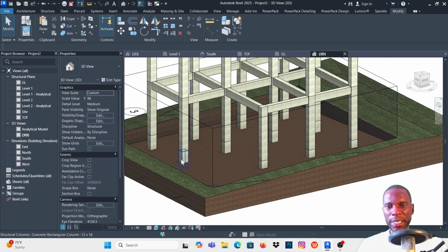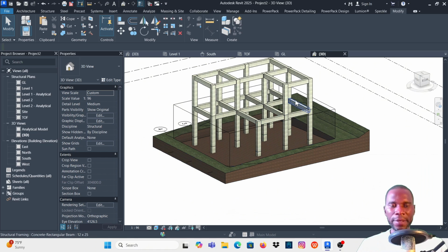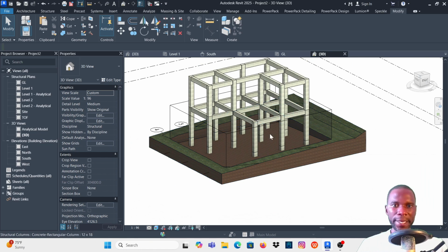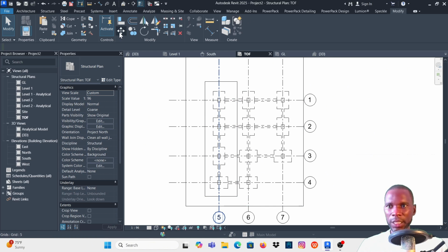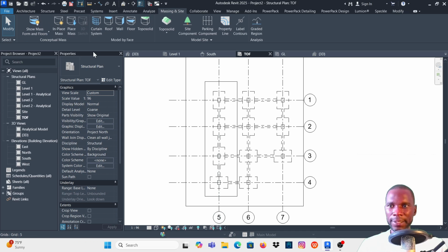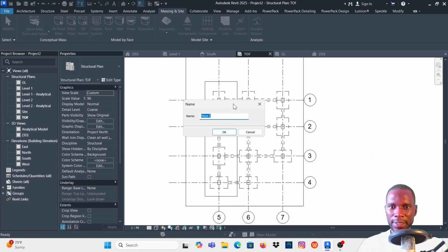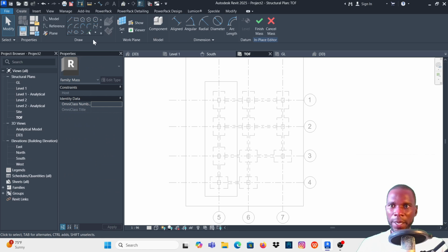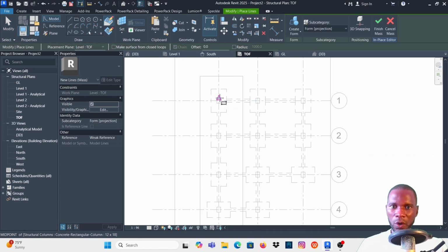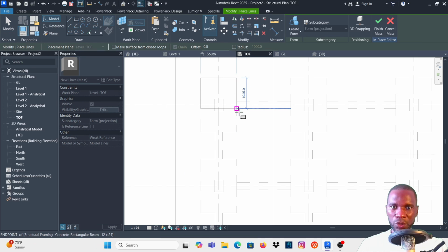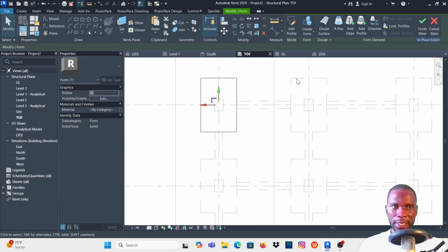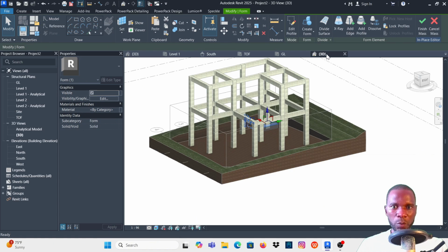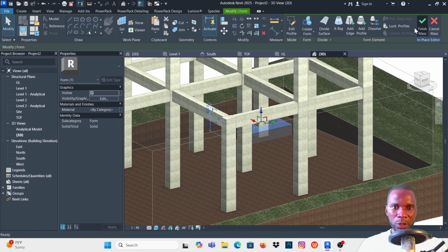All right, now we need to excavate the bases and the tie beams there. Again, I'll just go to the topo footing right here. And what I'm going to do is still the same thing. Just make sure that you go to massing and siting, then in place mass 2. I'll just click there, and I'm going to use a rectangle, and I'm just trying to trace these bases. Make sure that create form is selected. As you can see from here, I can go to my 3D view. The form has been created. Make sure that you click on finish.